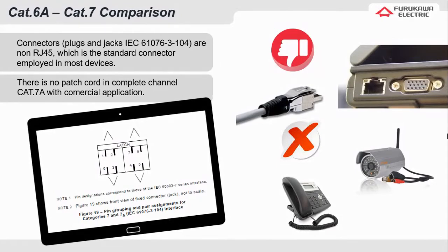So to attain the full advantages of CAT.7 higher performance, you would need a special connector. The one we have here, it's called GigaGate 45. But the thing is, you would not be able to plug this connector into any of your network devices. So using a CAT.7 cable with a CAT.6A connector will make our channel perform as though it was a CAT.6A channel. So there really is no point in using CAT.7 cabling.